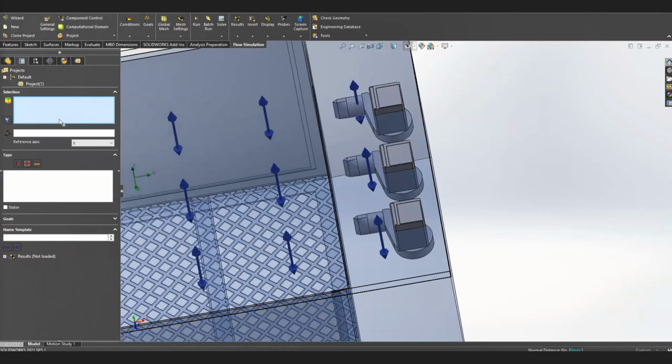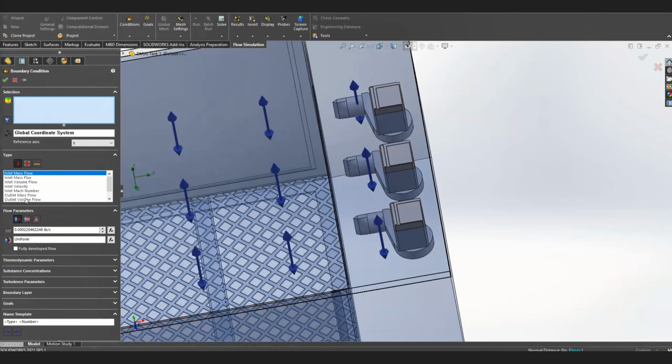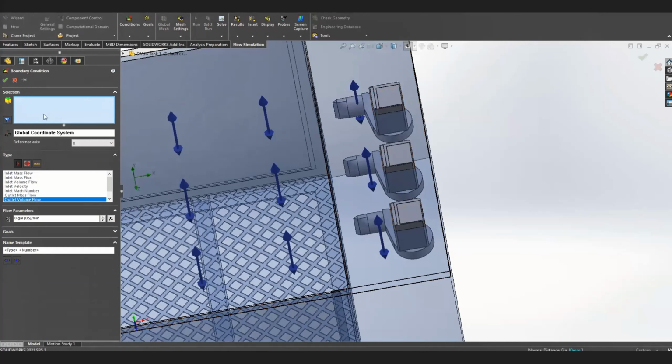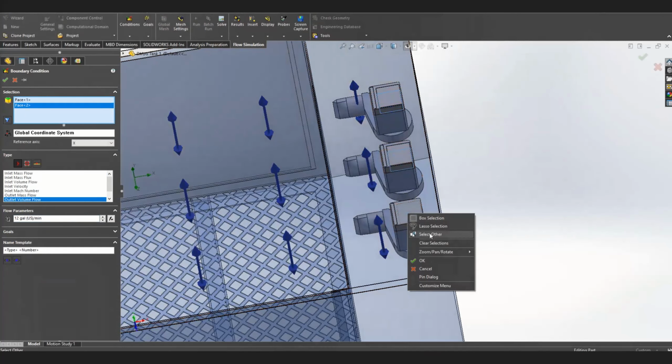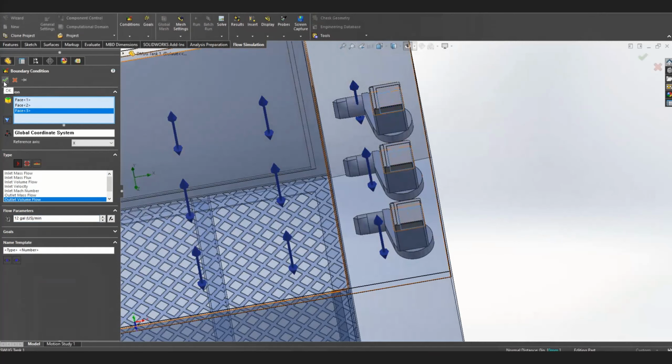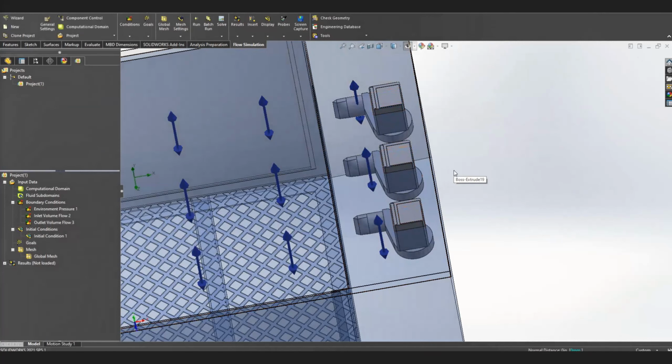In that case, also what I did there, sorry, I missed it while I was on the screen, but I set the inlet water at 158 degrees, just slightly above my 156. And that's so later you'll see I can better track the water flow in because I'll actually see the hotter water when I'm looking at temperature. Whereas if I just set everything to 156, I'd have to just base it on velocity vectors. It's much easier to see water flow through with temperature relations. Awesome.